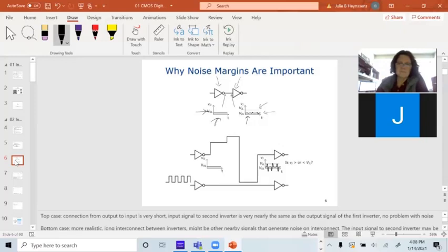Now the problem happens when I come through here and I've got a big chip and I need to route the output of this inverter to something that's sitting far away. And I'm going to have to go through a few gyrations and go through some 90-degree angles, which tend to distort my signal also on that routing. And instead of having this nice smooth output that I put out from inverter 1, I have bigger fluctuations because of my routing on inverter 2.